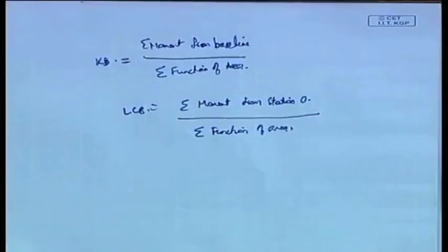You can find the volume, you can find the LCB, you can find the Kb. All of that is possible from a Buoyancy sheet. So, you can see the importance of Buoyancy sheet. Most of you who will go into the naval architecture career in shipyards or consultancy companies will be doing a lot of this Buoyancy sheet work. You will definitely have to calculate the volume submerged, and the LCB, Kb, etc. you will have to find out. Okay. Now, that is one thing.